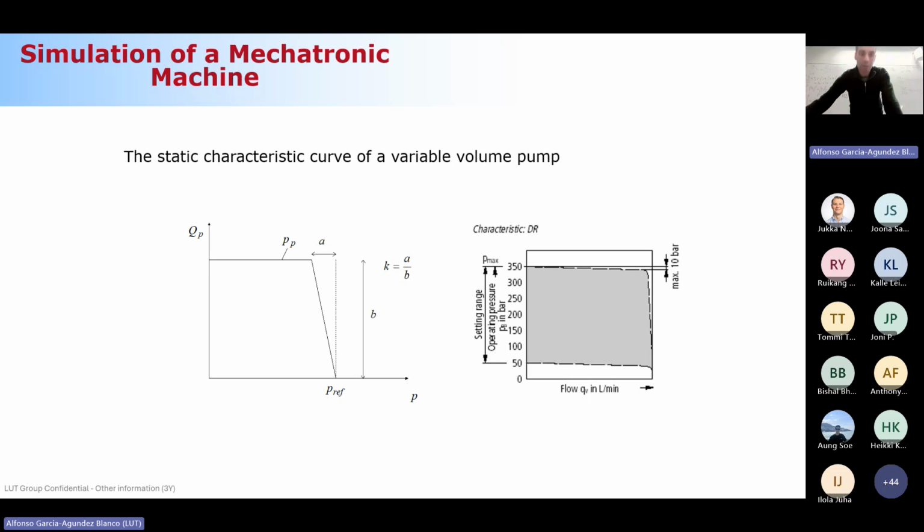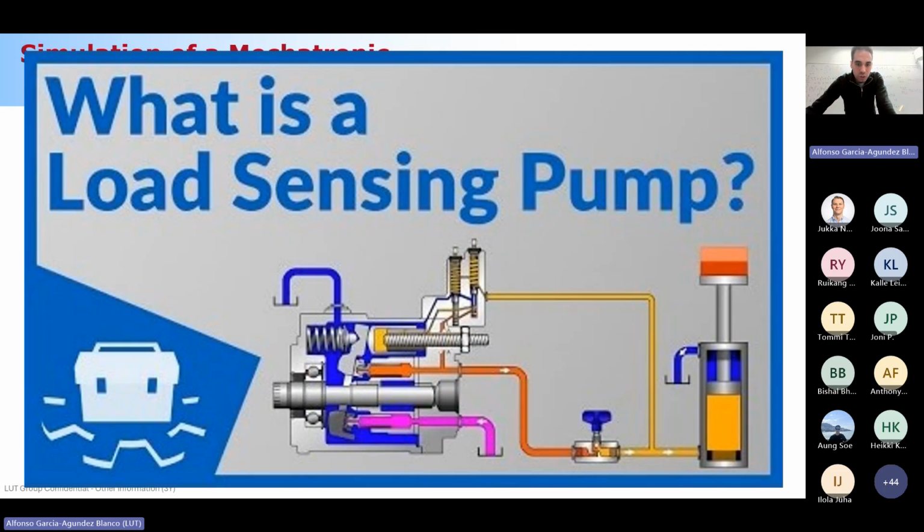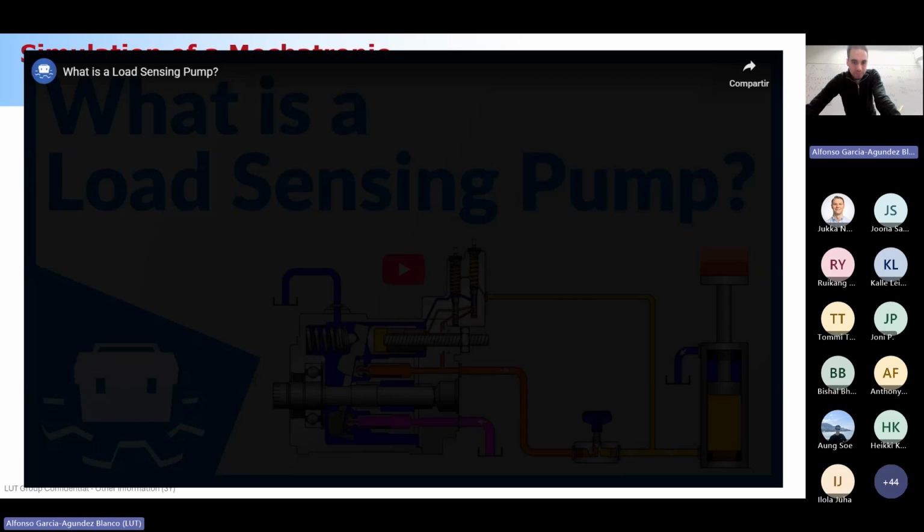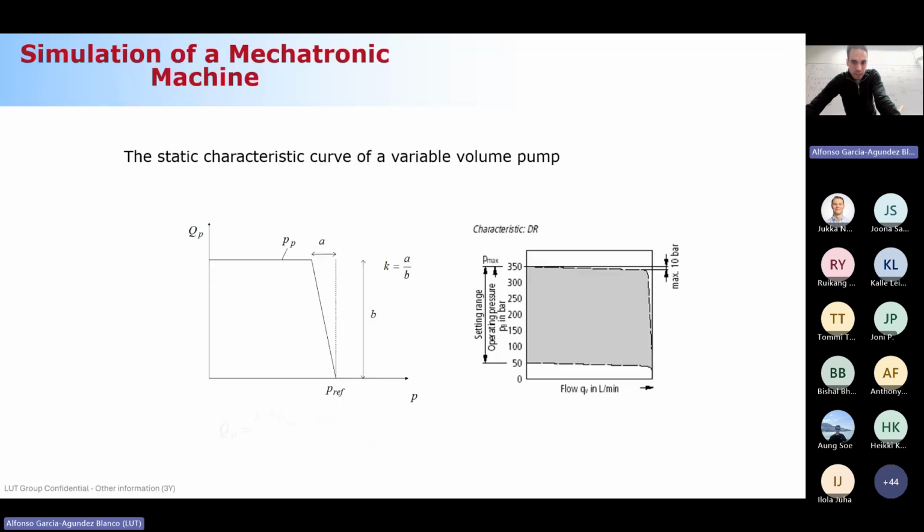In a steady configuration, I mean that if you go to the differential equation here, a steady configuration means that your time derivative is equal to 0, okay? So basically, if you make this derivative equal to 0, you can obtain a relation between the volumetric flow rate and the pressure, okay? And if you make this 0, you will obtain a linear relation between the volumetric flow rate and the pressure. That is what is depicted in this figure, okay?